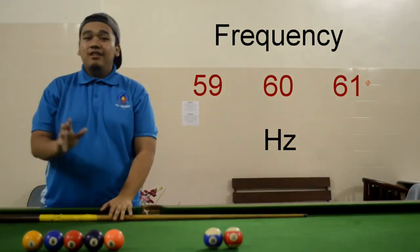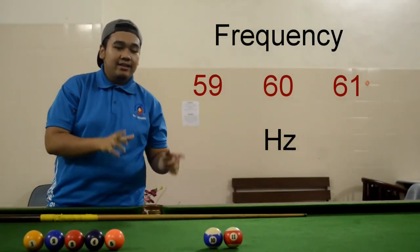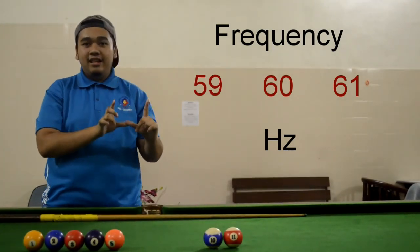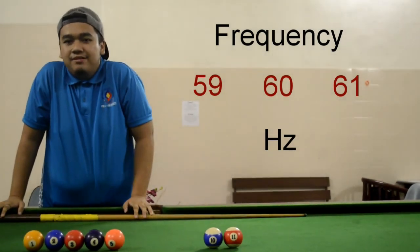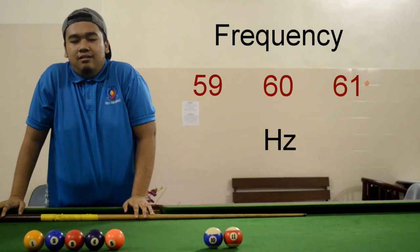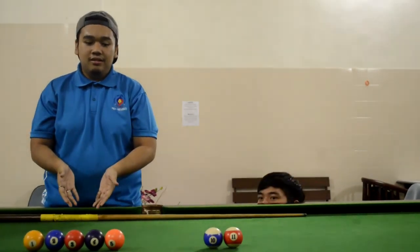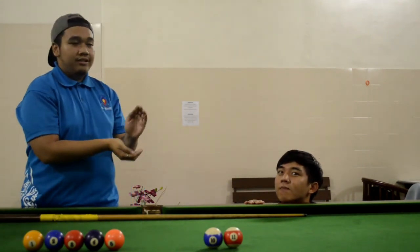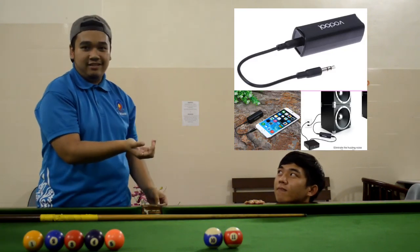This means all the frequency will pass through the power line, except for 59, 60, and 61. This means the main hum is filtered. Because main hum, if you want to know, is, for example, you have a speaker and you have a power line of 60 Hz.